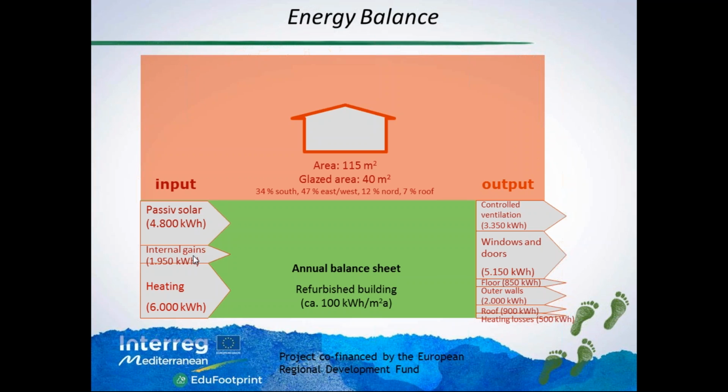Also, the passive gains are reduced. The figures here were higher before; those are smaller, not because there is cloudy weather, but because by reducing the demand of the building, the needs of the building, the part of the solar that we can really use is also reduced. That means that if we have already reached 20 degrees and we still have the sun shining through the windows, we cannot account into the balance the energy used to increase from 20 degrees to 25 degrees.